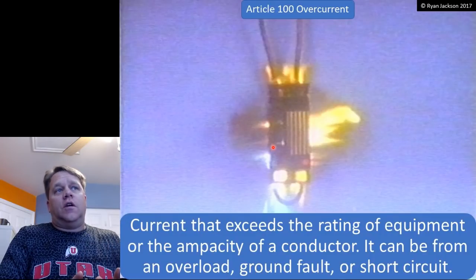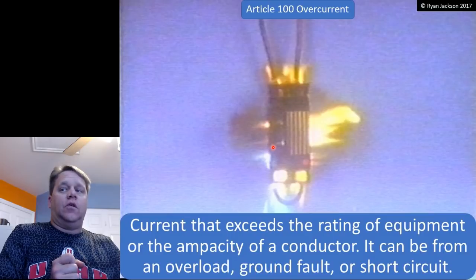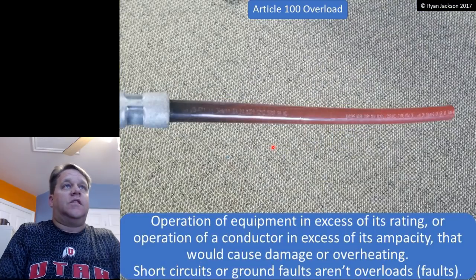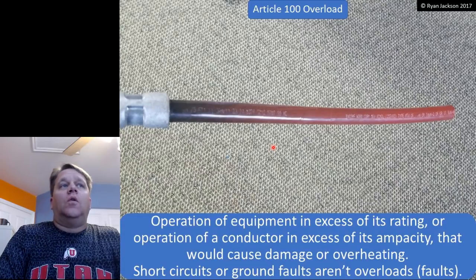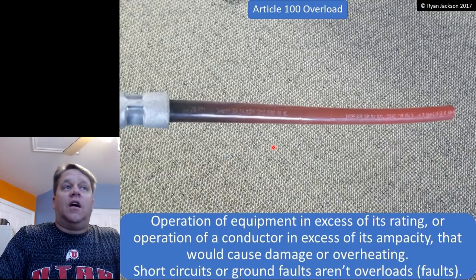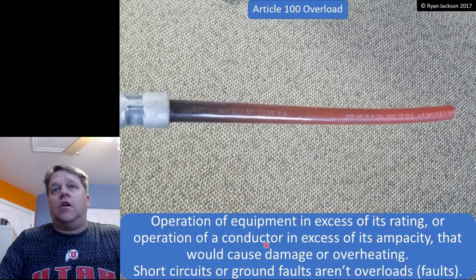So overcurrent can be from an overload, or a ground fault, or a short circuit. Any of those three creates overcurrent, and protection against overcurrent is protection against all three of those. Let's keep going. Overload. Overload is operation of equipment in excess of its rating, or operation of a conductor in excess of its ampacity that would cause damage or overheating if it persists for a long enough duration of time. Short circuits and ground faults are not overloads.